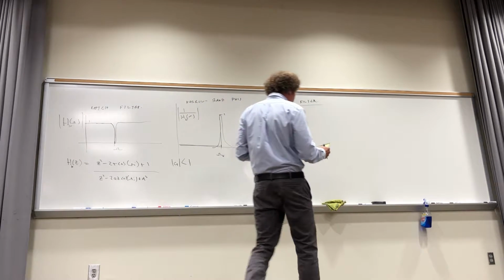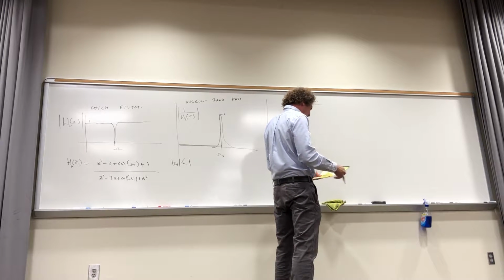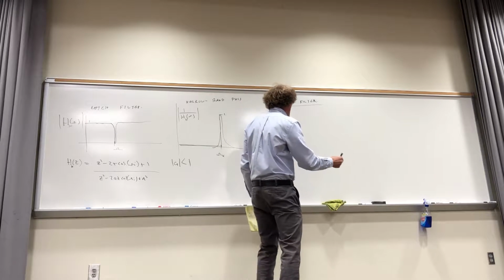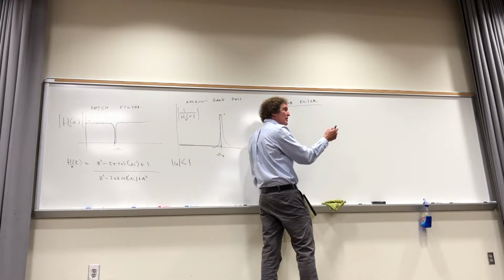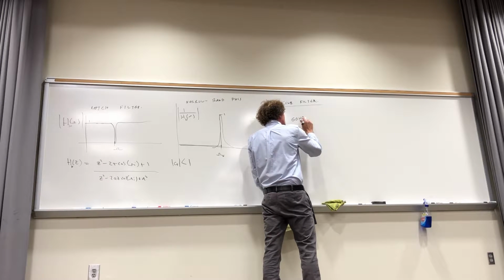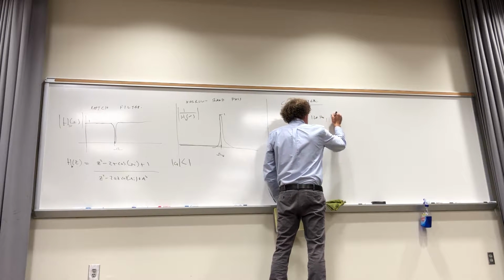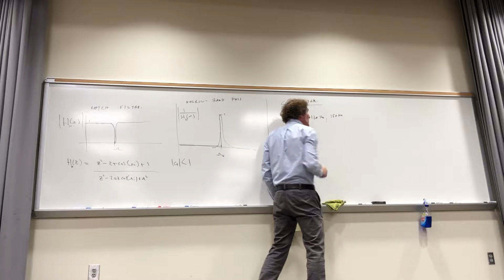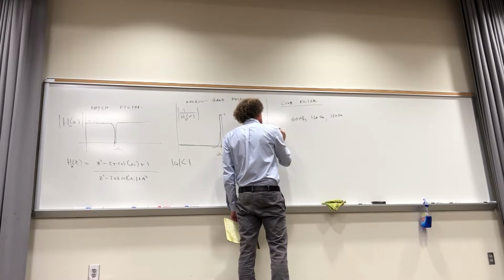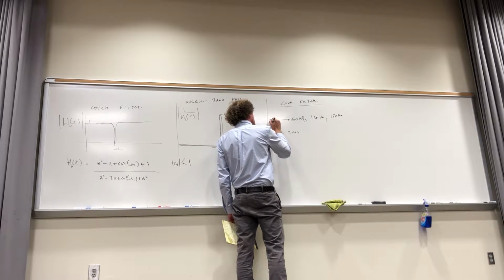So now with the comb filter, let me go through this, and I chose this because this is a real world scenario. So in the comb filter, you can do it 2 or 3 different ways, 2 ways basically. Suppose I had 3 frequencies I wanted to get rid of. If I had 60 hertz, all right, in the book he talks about this, I have 120 hertz signal, and I have 180 hertz signal. And I want to get rid of all those frequencies, but I want to pass 30 hertz. So I want to pass 30 hertz. These I want to eliminate.